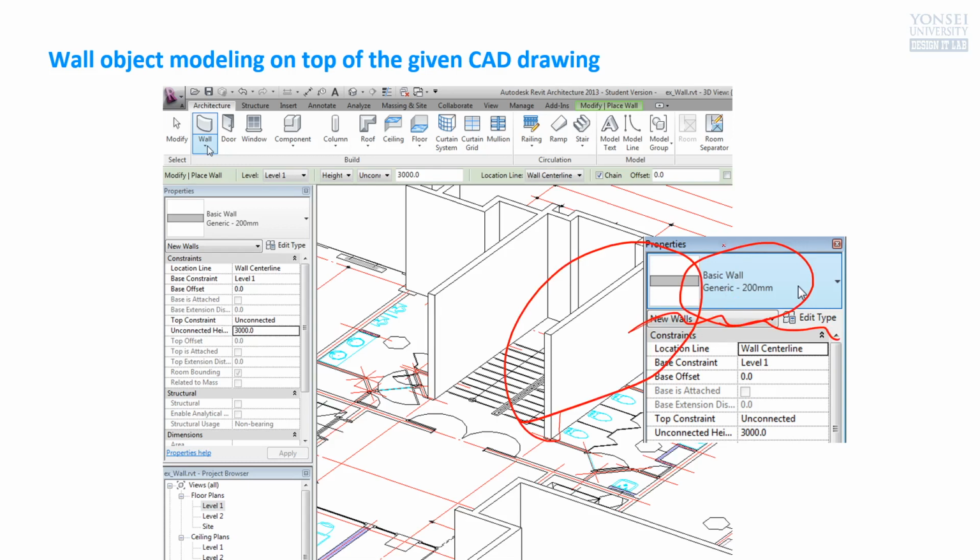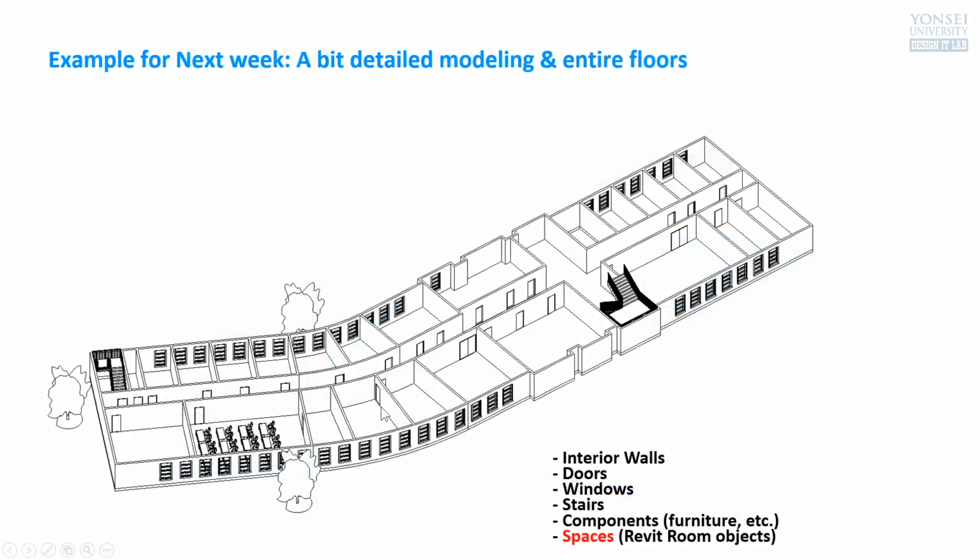This is sort of default wall in Revit. In US metric library template, any wall object you can replace, you can change, modify after that. So getting started your modeling using generic 200 millimeter wall, that's good enough. Okay, so you are familiar with this building. This is Samsung Hall, Samsung관. Okay, Samsung Hall level 5, where the floor where I am now. Okay, anyway, this is the entire floor objects modeled.